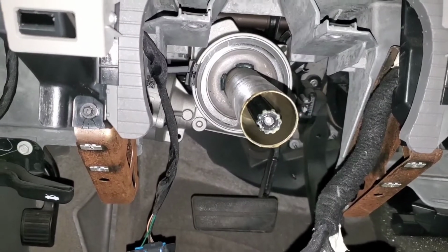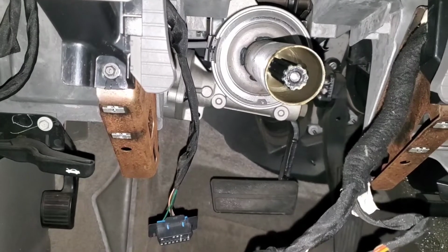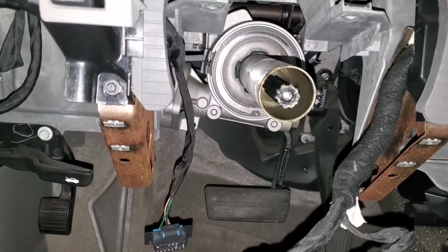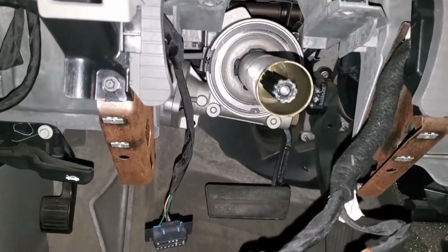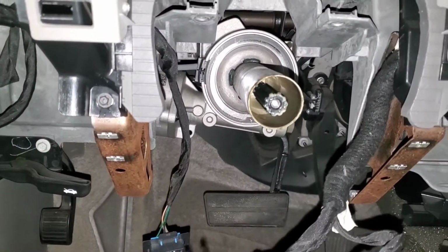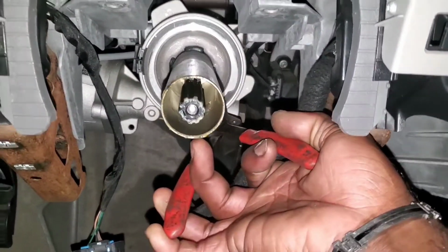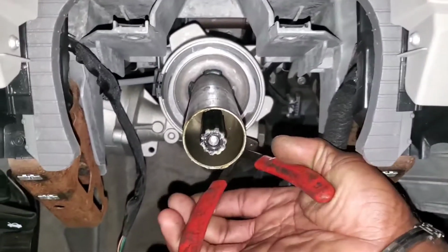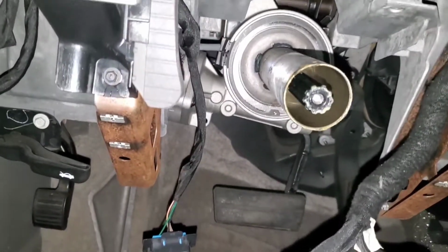Now, I think the reason why we're having an issue and why it's rattling back and forth is that there must be a dead spot somewhere in the torque sensor, since it's in a feedback loop. Similar to, has anybody ever heard of the HVAC system control actuators when they start going bad, or automatic side view mirrors? When they have a dead spot, they rattle back and forth in between the spot that's bad. Now, I guess because of how much torque and how fast this motor has to respond, if it does that enough, it shuts down, disables the system, and sets a fault.